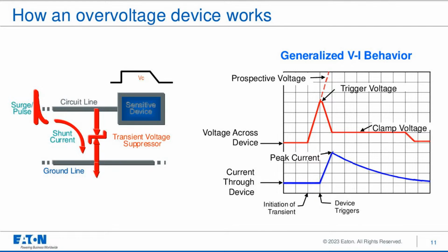During normal operation, with the circuit at or below the diode's reverse standoff voltage, the diode does not conduct, and its low leakage current and low capacitance make it virtually transparent to the circuit. When an overvoltage event occurs and voltage begins to rise in the circuit, the TVS diode enters breakdown and shunts the incoming current to ground, keeping the voltage seen by the circuit at the diode's clamping voltage and preventing damage.